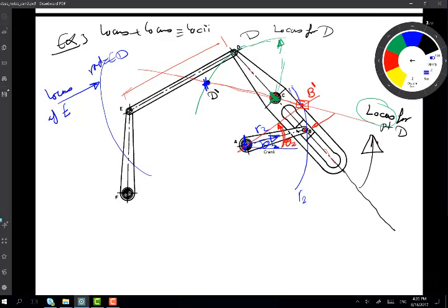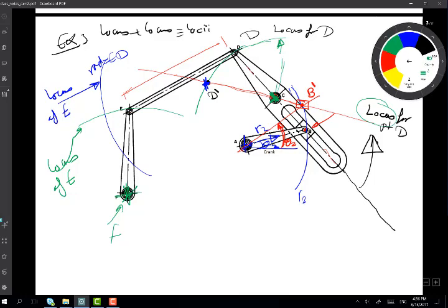This should be simple enough because I know E moves at a constant distance from F, this end here. So I can draw a circular arc where E always falls. So that becomes straight away the locus of E. Now I have to decide where point E is going to fall at the intersection. So this now says I have my point E prime right here at the new position.